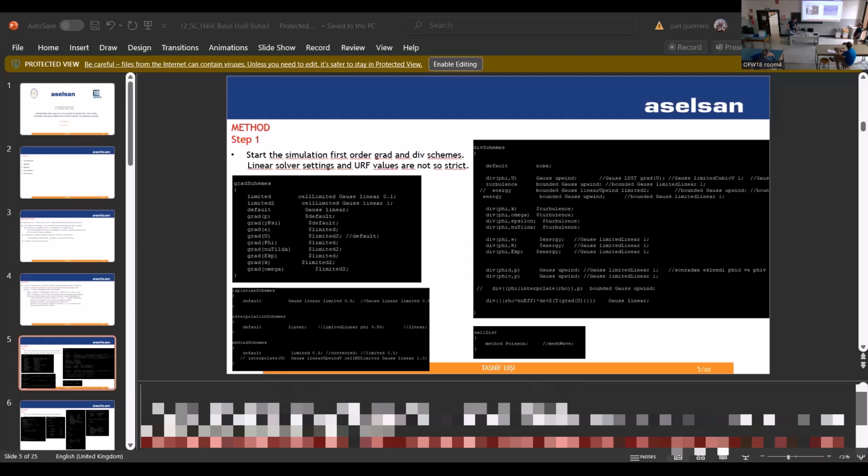So this is the second experiment, the DLR F6, which also has a skewness of 72 degrees. The surface mesh is from Pointwise, and the volume mesh is from Fluent Meshing. It also has 12 boundary layers created, so it's highly skewed. This CP distribution again conforms well with the results.